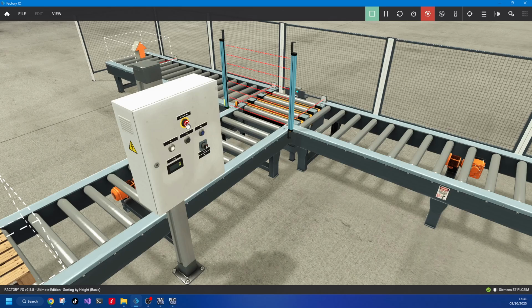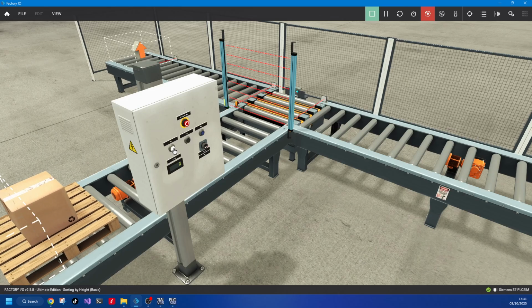We've got E-stop, so we can hit the E-stop, let go of the E-stop, but I still can't do anything. So one of the conditions in the code that you look at is we need to switch over into auto, hit start, and we should get going.